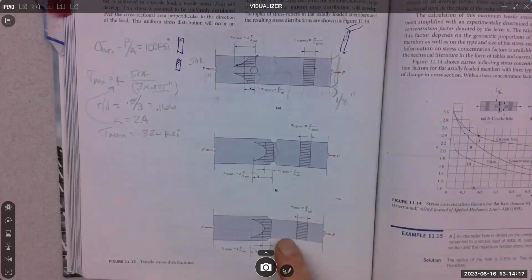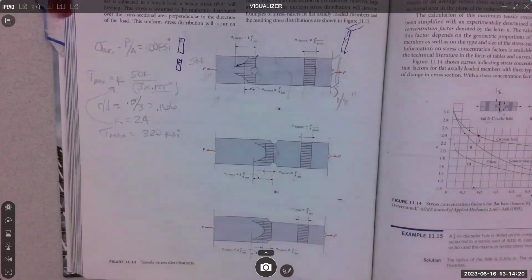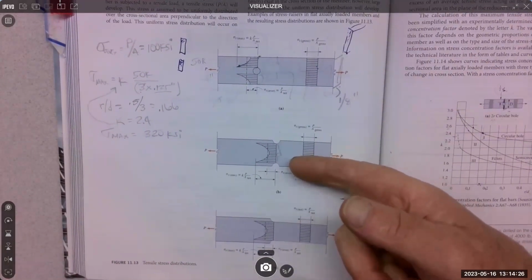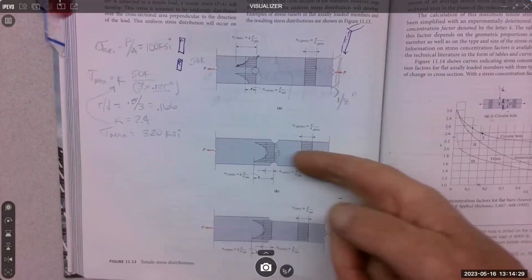Okay. The other one that's pretty common is the cross section changes. So it goes from a big cross section to a smaller cross section. So those are very common. This one, I don't really know the situation where we put notches in it, but this is the other one they did. So those are the only three cases that we can actually calculate in this class. Beyond that, it gets trickier, if the cross section goes from a circular shape to an elliptical shape to a polygon shape, like a cam shaft or some kind of shaft, that's beyond our scope.